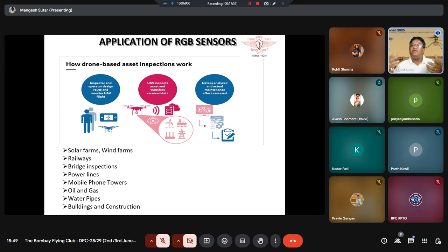Possibly those wires will wear out very fast, or they will oxidize very fast, or over a period of time they will break. The wires are always heating in the daytime because of the power being transmitted, and cooling down in the evening and night. This continuous temperature variation in the material causes deformity, and eventually some day it will become fragile and break.